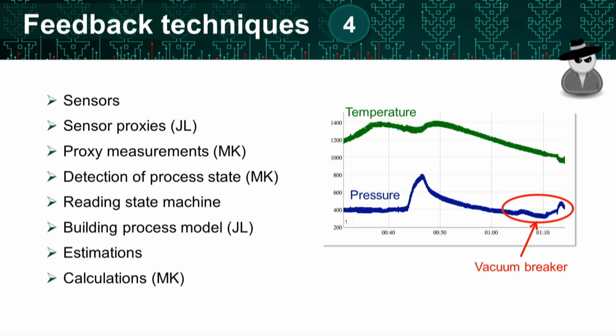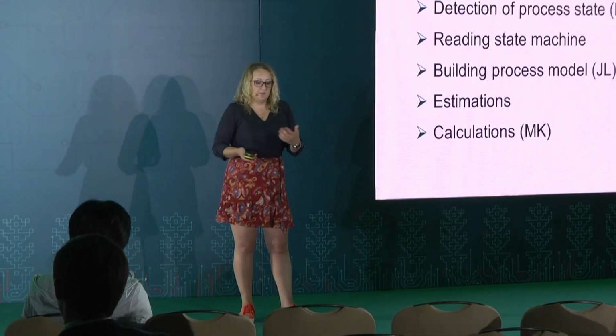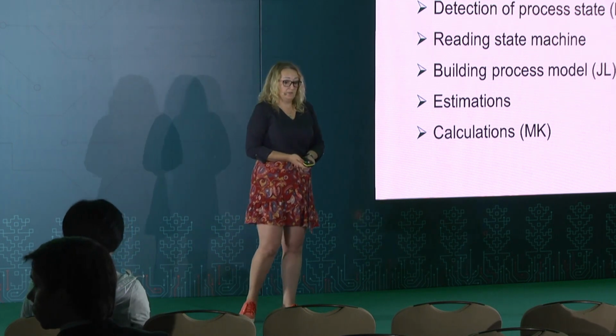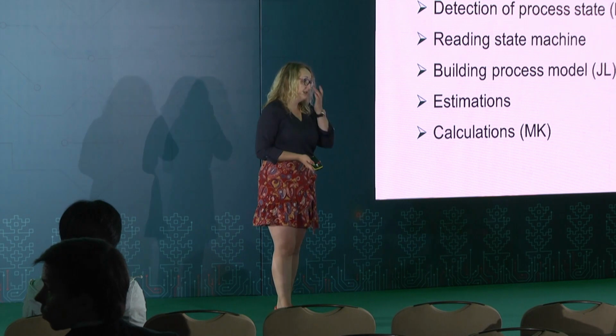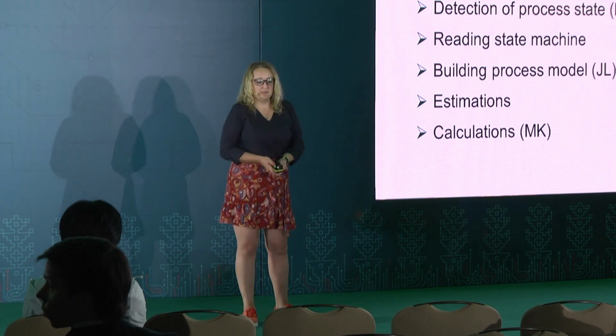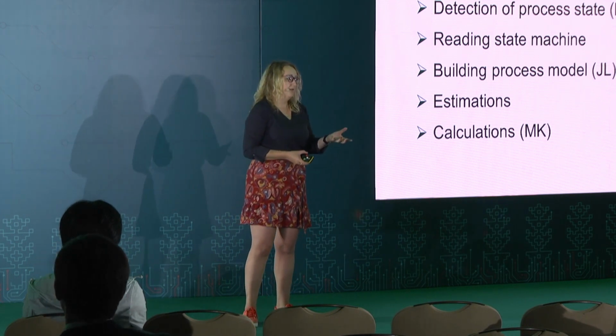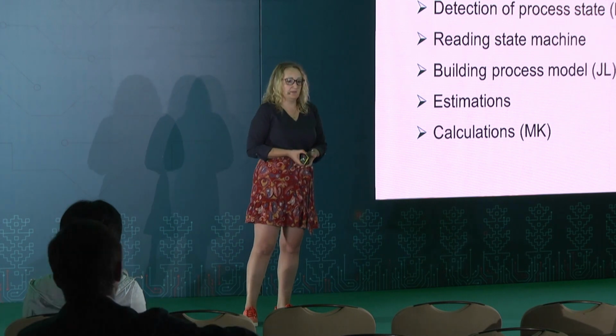We are sitting remotely somewhere far away, we can't see, and there is no roundness sensor which will tell us whether it has already imploded or not. So one of the indirect ways to do so is to observe the pressure in the pipe, and typically this sensor will be available. But, for example, if there is a protection like a vacuum breaker, then we will not be able to execute our attack.